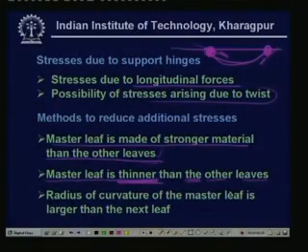If you make it thin, then the stresses will reduce at the extremes, because your y is reducing. But that is also one possible way; what people do is the other one: the radius of curvature of the master leaf is larger than the next leaf.